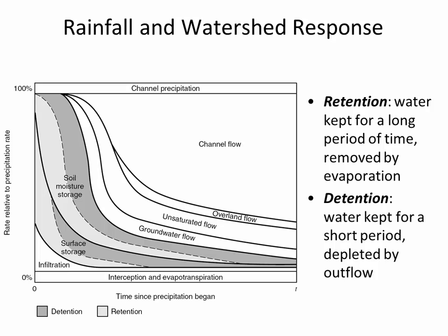And so the infiltration rate, which we've been talking about, starts high, and then infiltration rate is decreasing as the storm goes on, and then finally it reaches a plateau. Like it sort of reaches a constant rate. We looked at a diagram a few slides ago that explains this phenomenon. Why is it that infiltration rate begins high but then decreases?